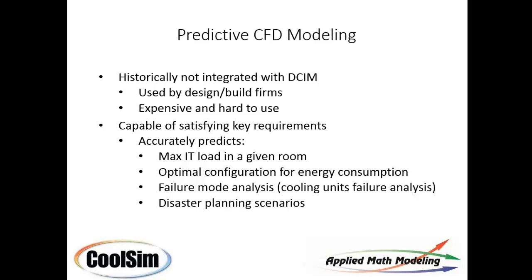I'm using kilowatt here in both terms of power and thermal load because it's the same unit, and it's easy to talk about it from that point of view as opposed to tons or BTUs. I'm using kilowatts for both. The ratio should be about 4. For every 0.25 kilowatts of mechanical energy, you should be able to displace a kilowatt of thermal load. That would give you a COP of 4 or roughly a PUE of 1.25, and that's generally how that works.